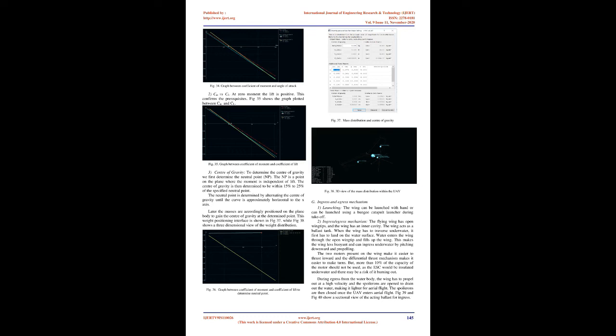by comparing lift gradient, viscous drag, pressure gradient, and streamlines for air at angle of attack 2.5 and 0 deg, and water at angle of attack 2.5 deg. With the decrease in angle of attack, to maintain the same lift the velocity is increased, thus increasing the drag on the plane wing and body. This can be seen with the high viscous drag at AOA 0, which compared to AOA 2.5 is higher.